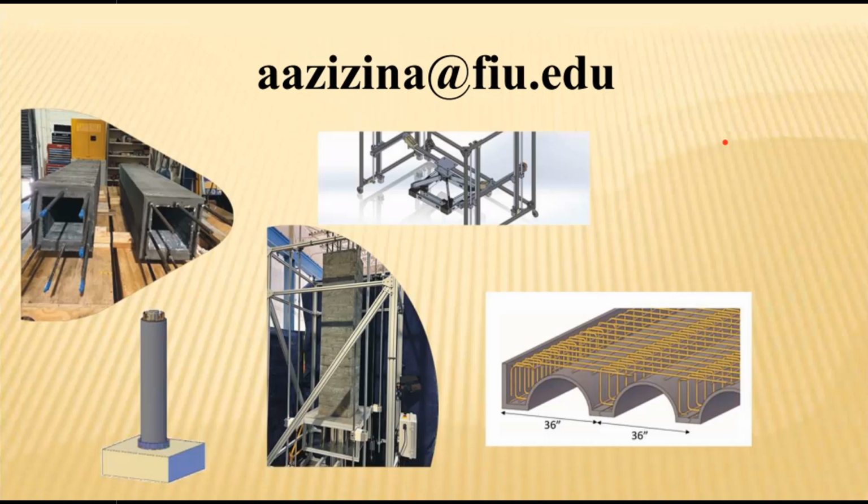So with the shell, I think you can achieve the ultimate strength of the shortest span bridge, but ultimately something is going to have to fail. In that case, you're going to get separation. In the test that we did on that 20-foot long beam, we did get fairly good behavior, but at the very end, we did have a separation between the shell and the normal strength concrete.